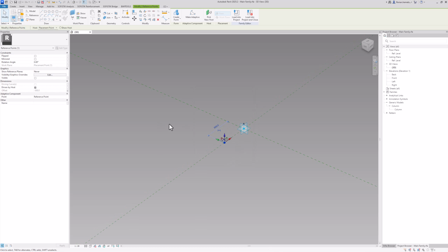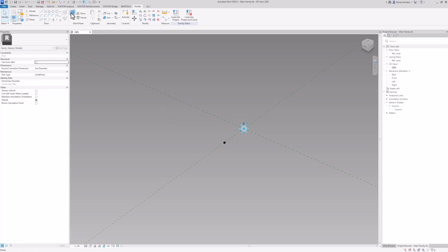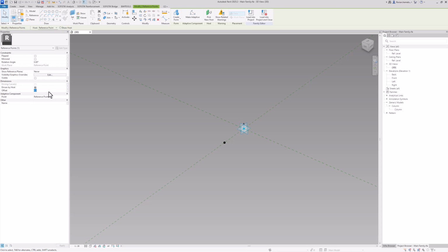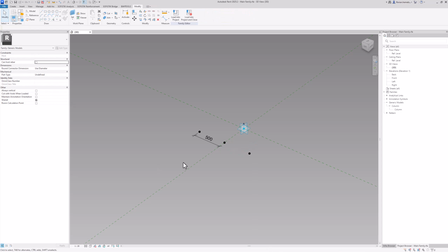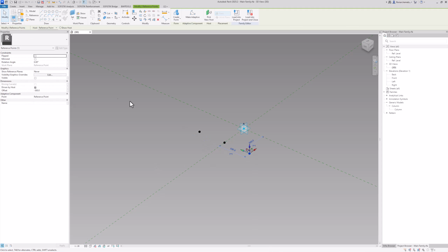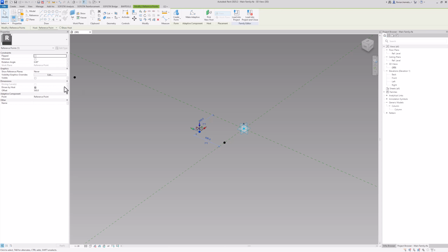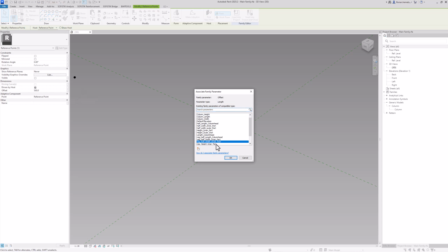We will need both. Because now, based on this insertion point, I will create all the other necessary points for this family. To do so, we first want 2 points here on top with the offset horizontally. You can see here I assigned a horizontal offset to this one, and to this parameter we want to assign the width of the column head, especially half width of the outer part, as well as the negative half width of the outer part.